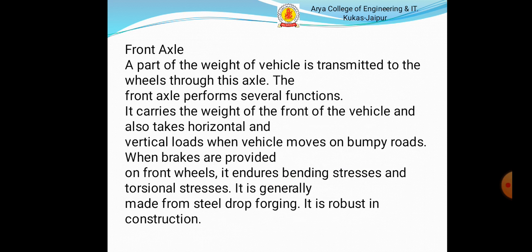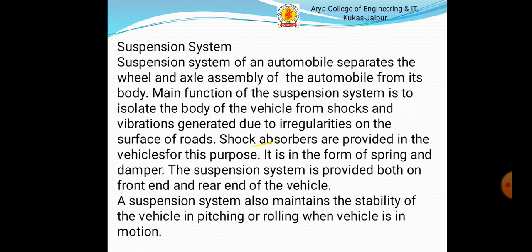Front axle. A part of the weight of the vehicle is transmitted to the wheels through this axle. The front axle performs several functions. It carries the weight of the front of the vehicle and also takes horizontal and vertical loads when the vehicle moves on bumpy roads. When brakes are provided on the front wheels, it endures bending stress and torsional stress. It is generally made from steel drop forging. It is robust in construction.